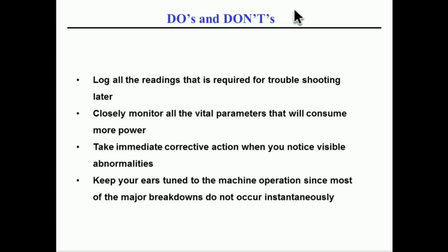One is efficiency. Not only efficiency, it is also going to lead to failure. For instance, running continuously with higher discharge pressure is going to consume more power, no doubt. But beyond that, it also means high discharge temperature, and it can lead to failure of the compressors. So take immediate action whenever anything is happening, and do not wait till everything comes to a head.